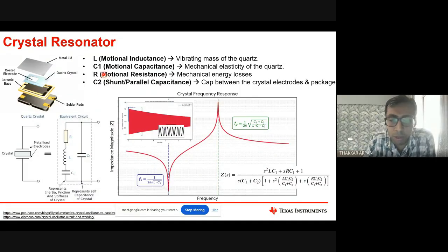Okay, so let's say you connect a cross couple pair here. You connect cross couple pair drain, and then another cross couple pair, you make a cross couple connection across these two terminals, and you leave it, right? So what will happen, depending on the current in the oscillator, is that current will switch one side and another side, and it will form a square wave.